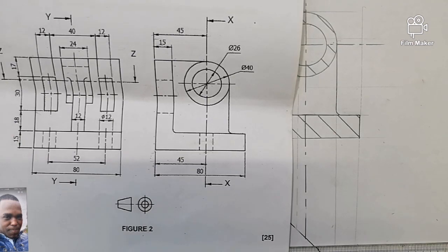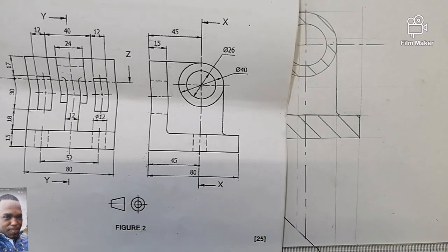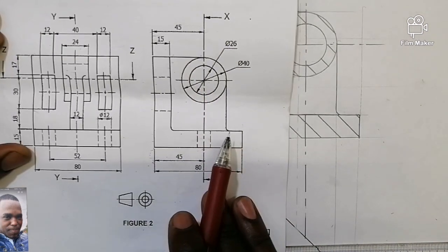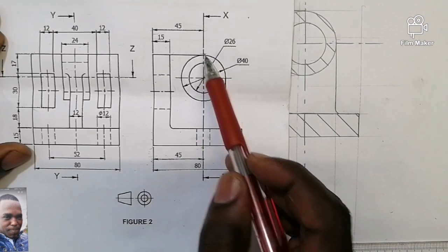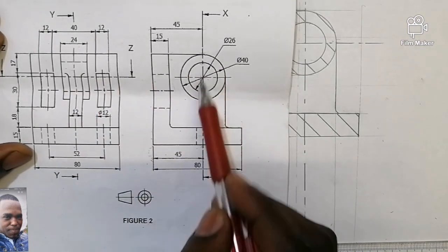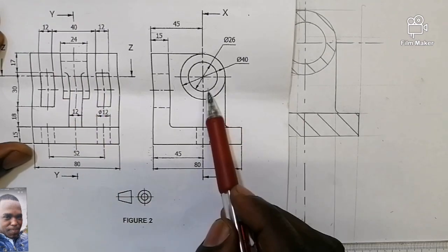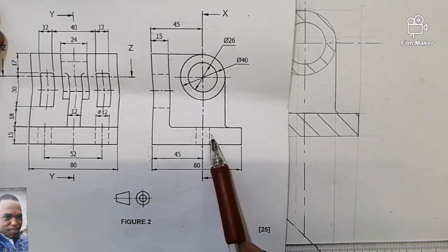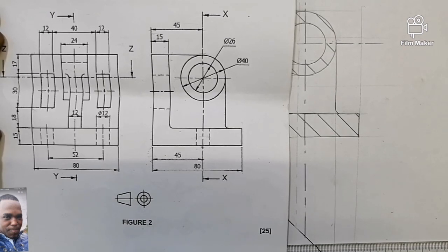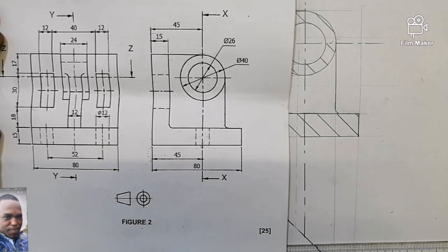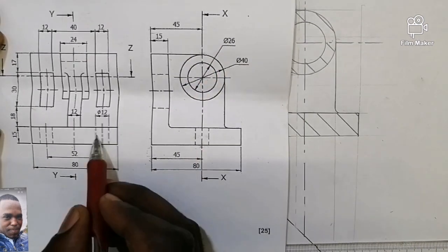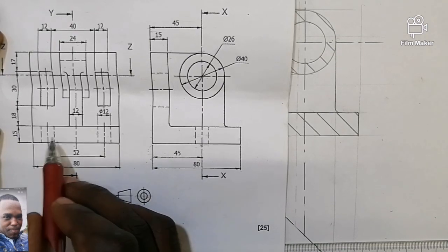Then what is left? Let's finish our front view by tracing the cutting plane of XX. So if we cut from here till here, which is this one, from here till here it's a hole, then from here till down there. Do you see that these two holes now, when you are viewing it according to the front view, are now going to be sectioned? It will be, because the cutting plane XX has cut through it. So this one and this one will change to dark.